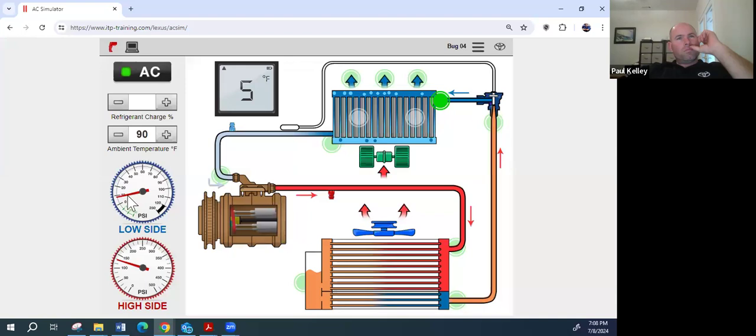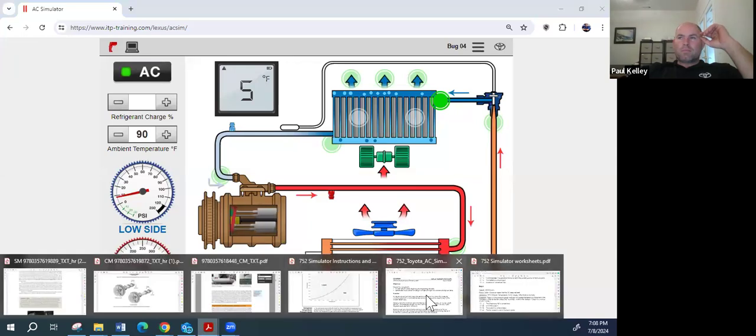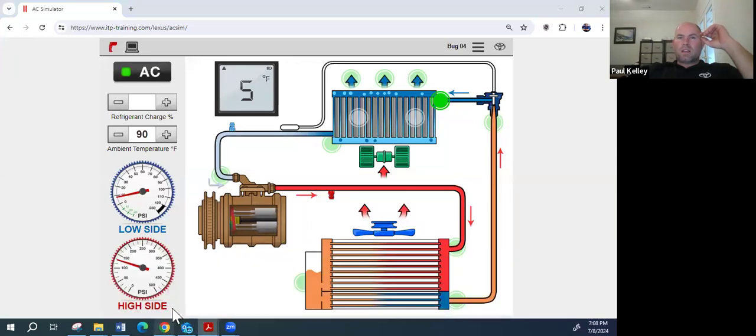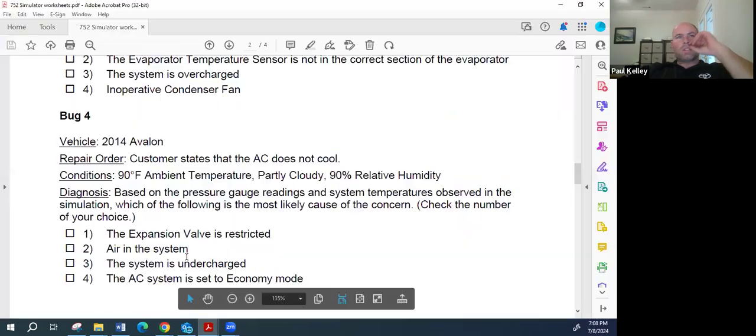But the low, no, a worn out compressor doesn't draw the low side below 10. That's like totally weird. How could the low side be almost into a suction state? Hey, you know what makes sense? It was that restriction, wasn't it?